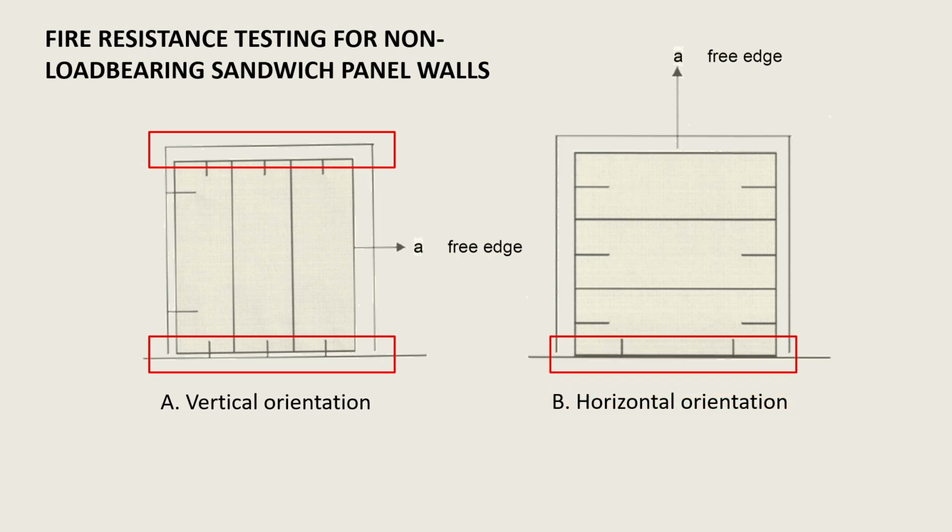For bottom connection, U-profile can be used instead of angle profile to simulate more severe fire conditions. It is also important to note that both faces can be separately fixed to the ceiling or floor or by through fixing.